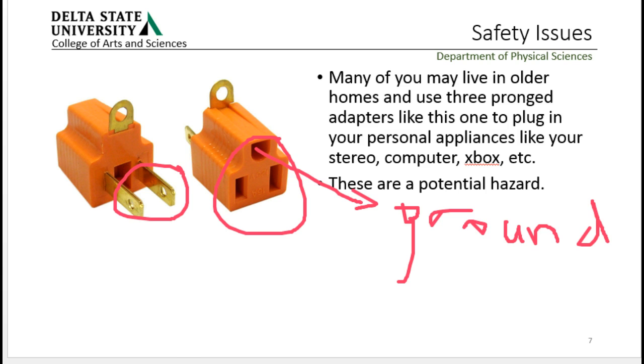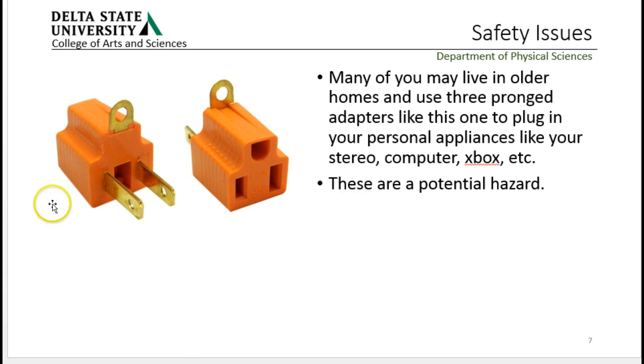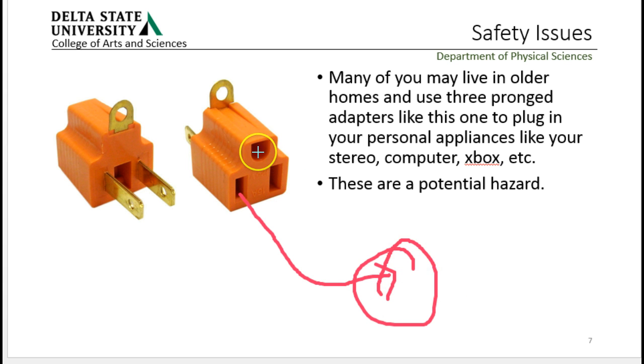Now, why are these allowed at all, you ask? Because they keep you from grounding your appliance, which means you're now grounded through the neutral, right? You're grounded through the neutral all the way back to wherever your power supply is. But your power supply is not necessarily anywhere nearby, which means if you don't have a local ground, this neutral can drift from local ground, and you, being attached to local ground, have to worry about that.